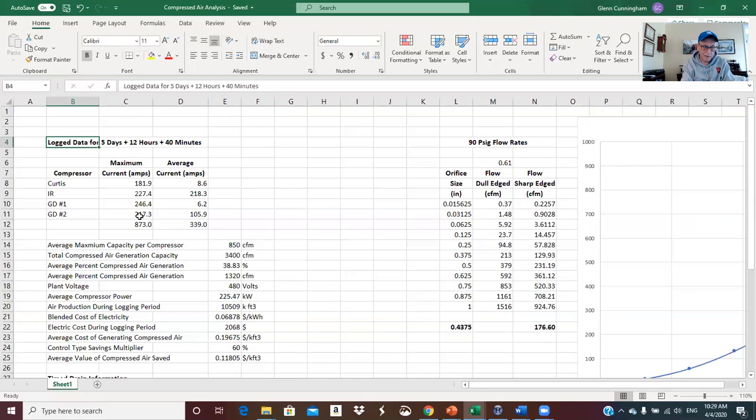And so the numbers turn out to be fairly significant. They can put one zero loss trap on the entire line coming off of the manifold that's receiving the flow from all 4 of these, and it'll reduce the amount of air loss as long as the trap's working right. They won't lose any air. So this is significant. I think right now it's about 176 CFM of savings, but we'll get there.